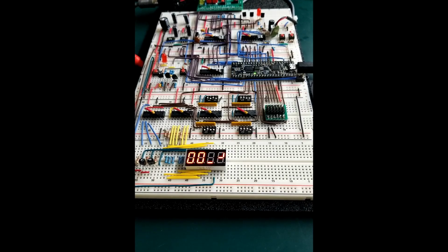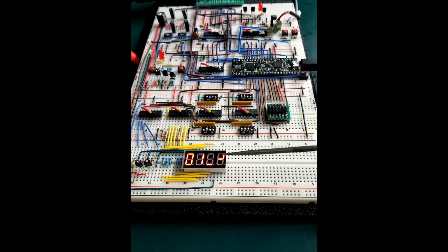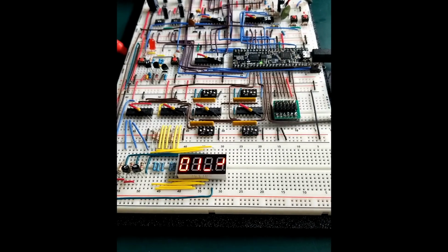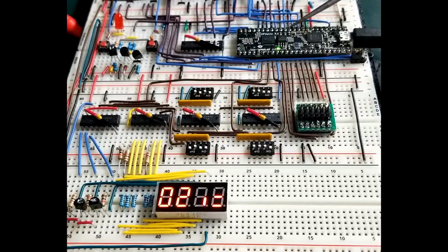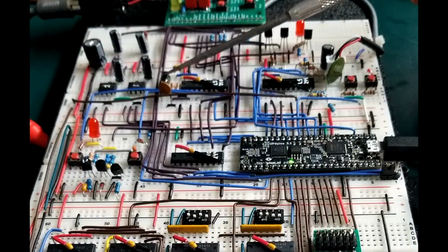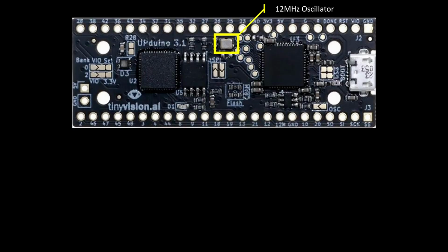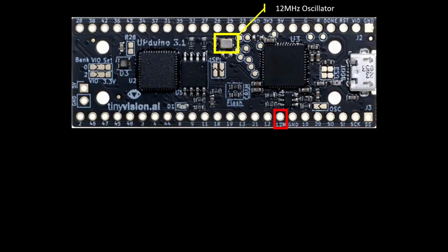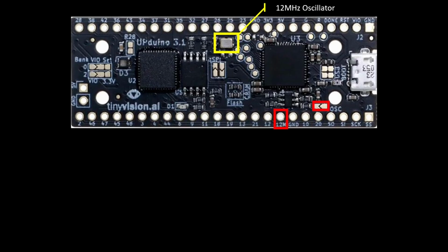In the last video, we finished the LED display. The last thing I want to do before we get to the circuit board is to see if we can use the 12 MHz onboard oscillator. We could then skip the 14.318 MHz parts. We can access the 12 MHz signal via the 12M pin, or we can also short this point to bring the 12 MHz signal directly to I/O pin 20.